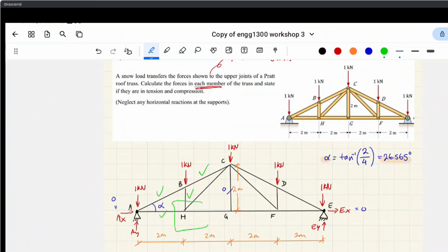And now we can move down to, well, actually you can go to two places. You can go to C. No, there'd be no reason to go to C because you've effectively solved for these as well, and the other ones are zero force. So you basically just go to H, because for G you don't know the information yet. So you go to H and solve for this member and this member now. That's exactly what we're going to do.